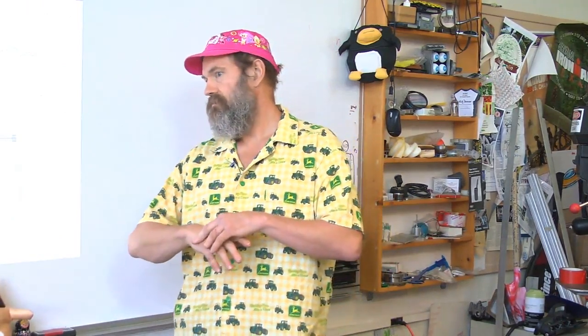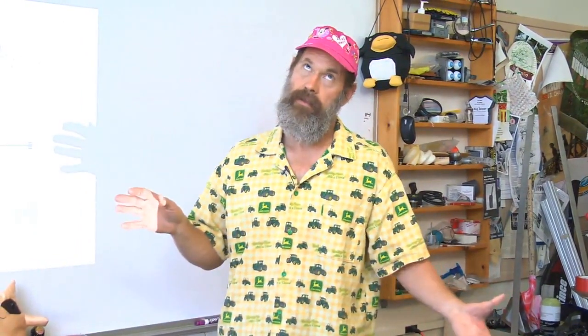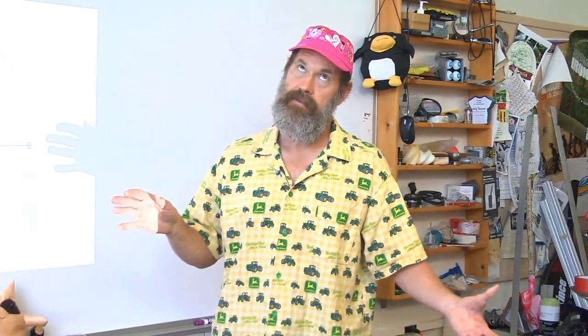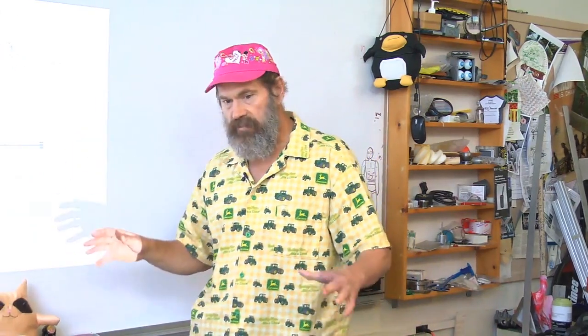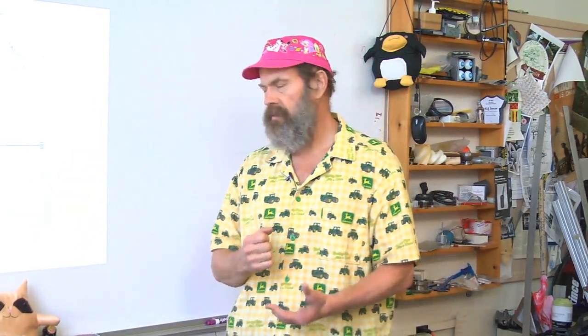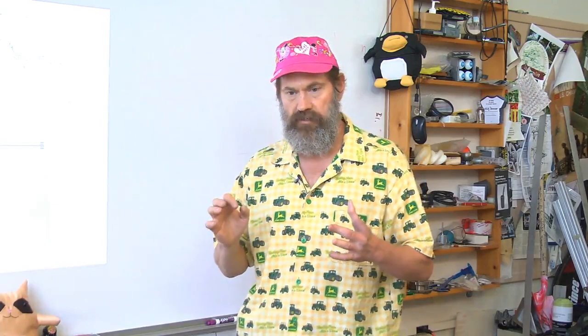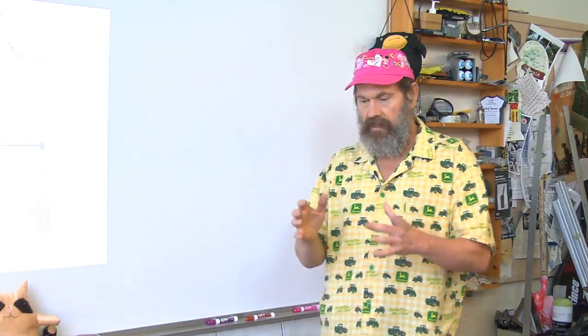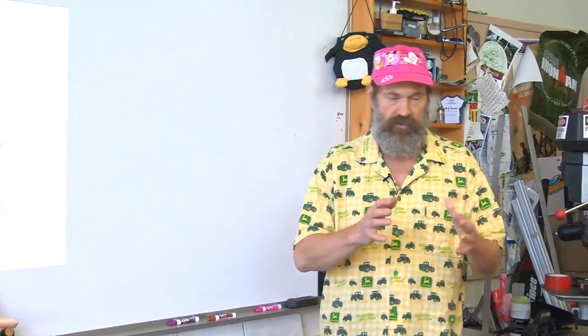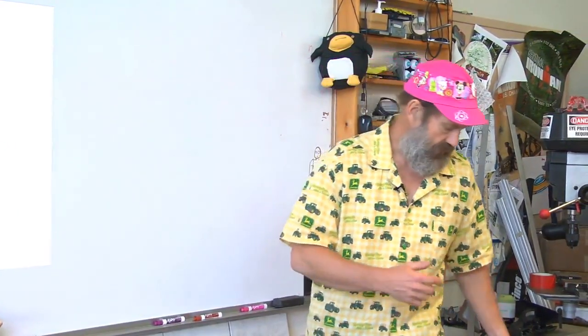So now let's talk about stability. Stability in your structure is very easy to achieve if there are no loads, nothing affects it. You can just sit here forever like this, right? But if you've got the wind blowing, you've got forces on it, you've got drilling, now you start having the issue of not only structural stability in terms of static loads, quasi-static loads, not causing, boom, for example, the shear center problem we showed earlier by pushing off axis on a beam, but dynamic loads exciting natural frequencies.